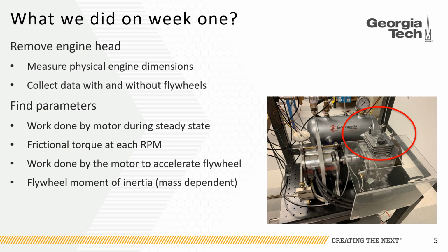Okay, moving into week one, the simple system we used was removing the engine head and just having the engine powered by the motor. We collected some physical engine dimensions, and we collected the data with and without flywheels. We are finding the work done by the motor during steady state, the frictional torque at each RPM, as well as the work done by the motor to accelerate the flywheel or flywheels. And then finally, the flywheel moment of inertia.